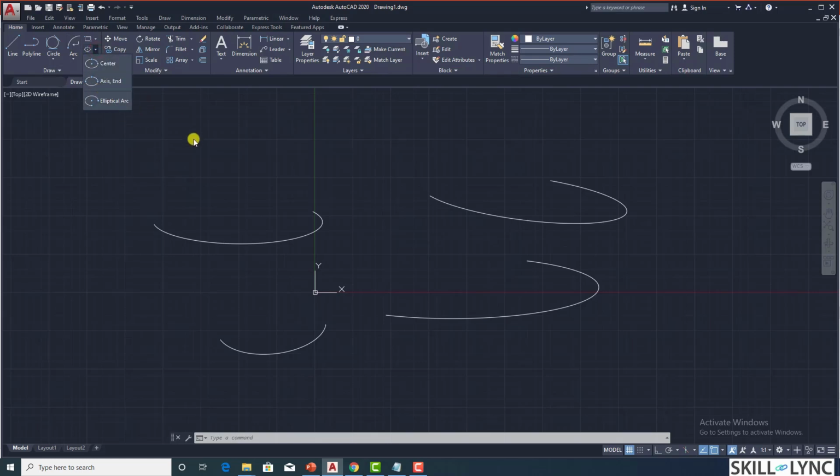So this is a perfect ellipse that you have drawn. But there is also a system variable called PELLIPSE, that is a polyline ellipse. You can see here you have the PELLIPSE. Now it is in the off condition, that is, it will create a true ellipse object. If you set it to 1, it's a PELLIPSE. Now you construct an ellipse.